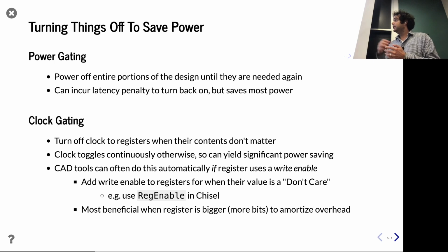What's the trade-off here? Well, first of all, you have to have the ability to cut the power off this component. That's some circuitry required for that. You also need to artificially have a design which can recognize the opportunity for this, and then have the ability to turn this component back on. And when you turn it back on, resynchronize, reconnect to the rest of your design, right? So sometimes turning things back on, there's some sort of latency penalty. But if you turn it off for long enough, this whole thing is worthwhile.